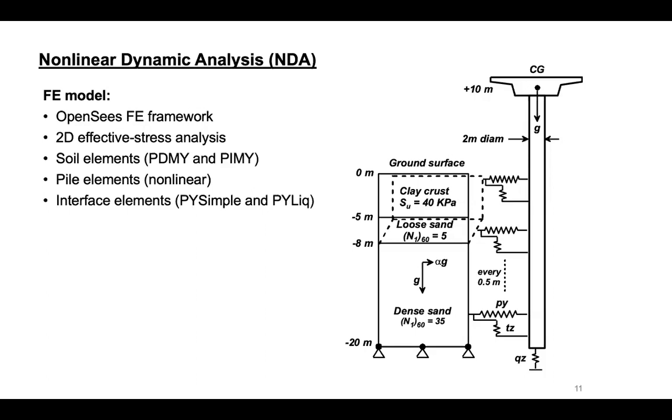This shows the schematic of our nonlinear dynamic analysis. It's a 2D analysis in a finite element framework. We use liquefaction constitutive models to model liquefaction of sand. We use fiber section elements to model nonlinear behavior of piles and formation of plastic hinge, and the piles and the soil elements are connected using interface springs.